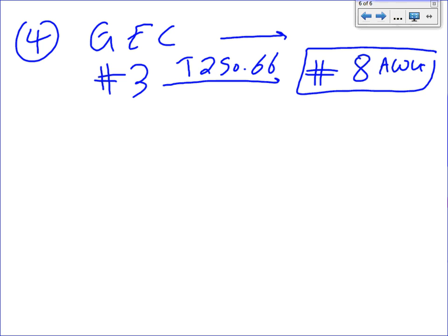That's why in residential, if you do the math, you end up with number 8, but we always pull number 6, even though you're allowed to go number 8 by code. You don't want to put in another conduit to protect it. And if you put it in an EMT, you have to lug both sides of the EMT to the conductor, creating more work for you. Okay, but strictly based on the code, number 5 is the main bonding jumper.